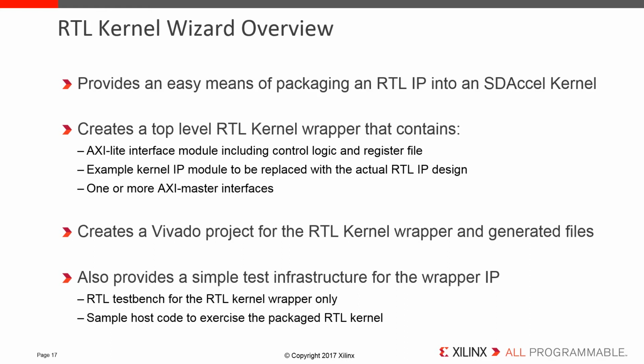RTL IP developers will need to ensure correct connectivity between the RTL IP and the wrapper template. The wizard also generates a Vivado project for the top-level RTL kernel wrapper and the generated file. This enables working in the Vivado environment to update and optimize the RTL kernel.